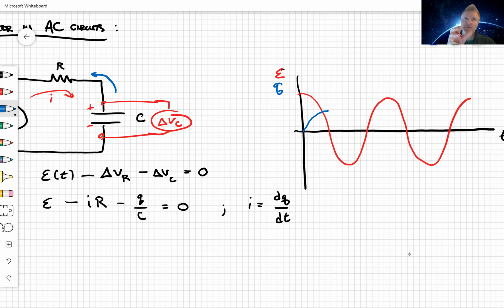Now, after some amount of time of the voltage being the other way and the current running in the other direction, it's now taken all the charge off the positive plate and put it on the bottom plate. But that's where all the negative was, so it's zeroed out the capacitor. Okay, and now it overshoots and says, I'm going to keep putting positive charge, I'm doing it at a decreasing rate though. I'm taking positive charge off the top plate, putting it on the bottom plate. So the bottom plate becomes positively charged and the top plate is negatively charged. And it reaches a peak.